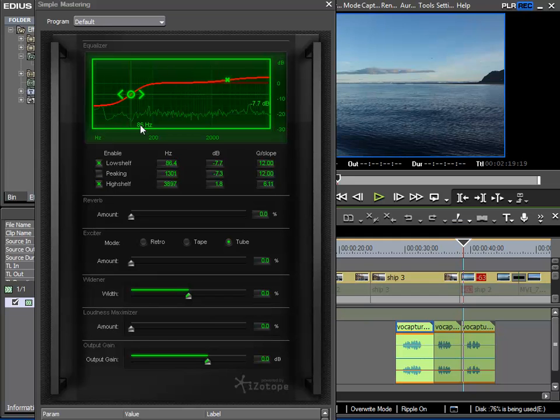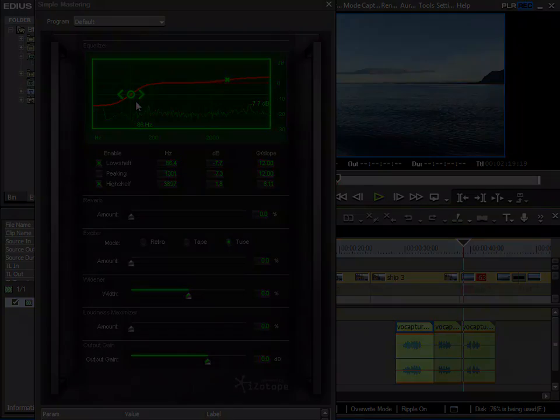Yes, and you probably noticed that if I adjust too far upwards with the low shelf, then part of my actual signal is cut off and the speech sounds very thin. I'd probably wish to cut everything below 100 Hz, as there wouldn't be much speech in that section, but there would be all the hum and the low-end noises that we would like to reduce.